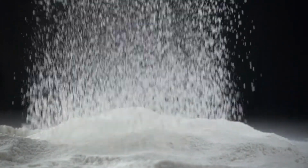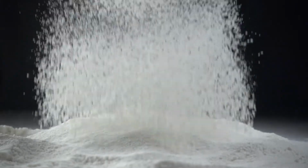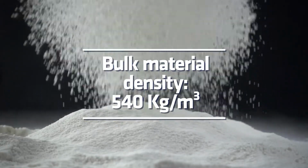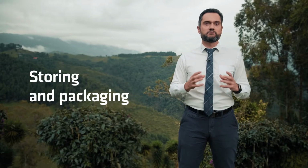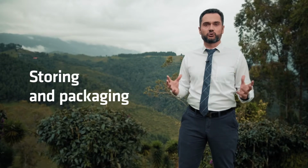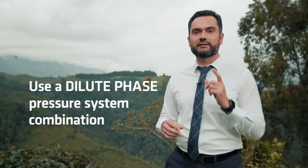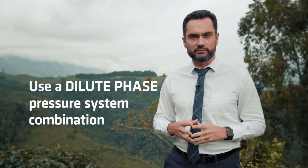Flour is a material with good air retention, which is a particle capability to retain airflow as it passes through, and has a light and small particle size and a bulk material density of 540 kilograms per cubic meter. Flour is produced in flour mills, where pneumatic conveying lines are used for storing and packaging the final product. Both applications use a dilute phase pressure system combination.